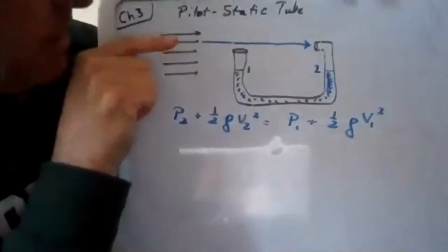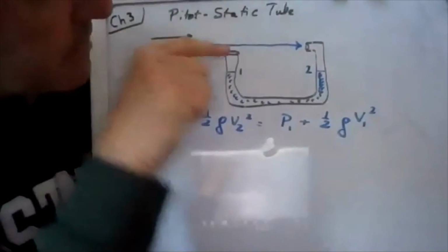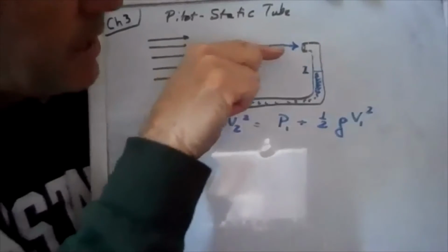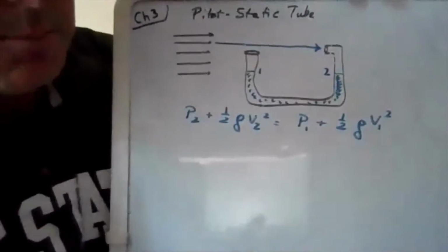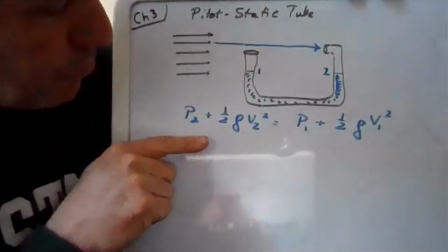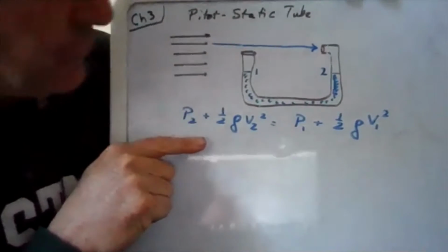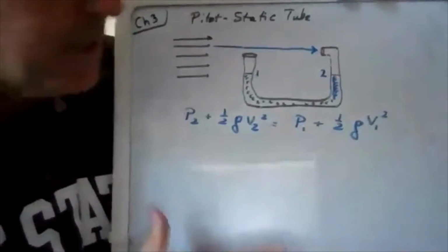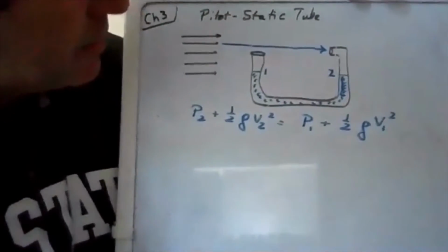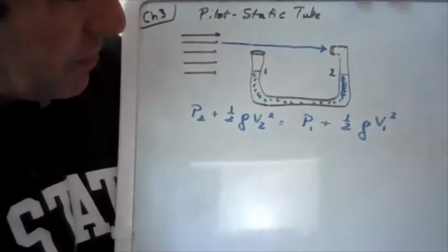All right, so one way of thinking about it is to take a look at just this streamline right here. It's coming along, it's passing right over the top of this opening, and it's going straight into that opening right there like that. Okay, you probably got it. It might also be worth writing the Bernoulli equation for that streamline. No z terms, because there's no change in elevation from this point here to this point here like that.